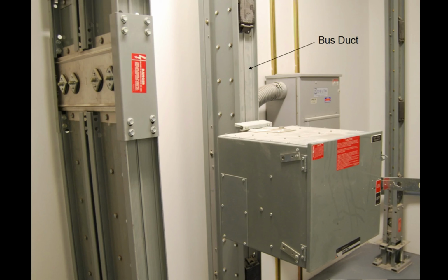Okay, this is the riser or bus duct that we described earlier. You can see how that allows for the conduit full of the cable, bringing the 480 up the building spine or wherever it's located, up to each individual floor level. As you can see, it's kind of armored and protected, so you can build in and around it as the levels go up.